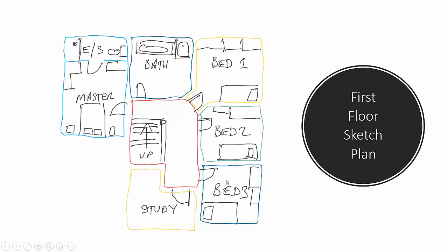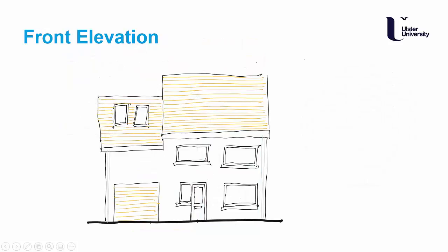Definitely within your spaces you should be putting standard sizes of furniture, and the Metric Handbook is very useful in that regard. It will give you standard sizes for beds and baths and toilets and all the different things that you need. I have not put any furniture in the study, but all the other rooms have bits of furniture in there just to try and help with the arrangement and understanding if it will work from a functional point of view. What you definitely need to make sure is that you have door access at all the relevant positions.